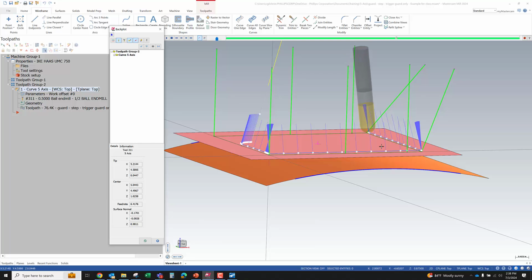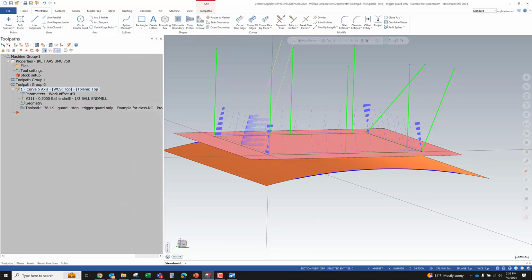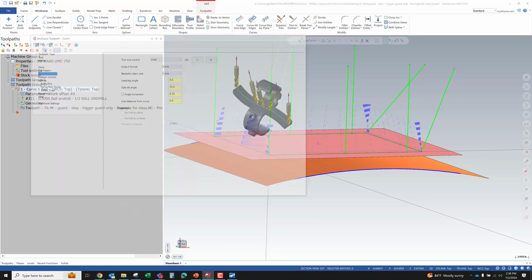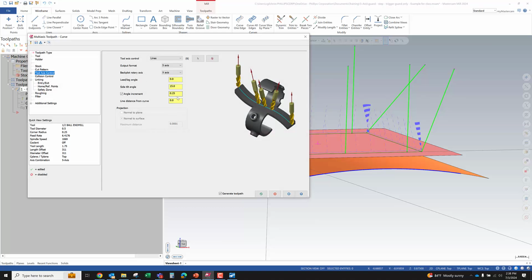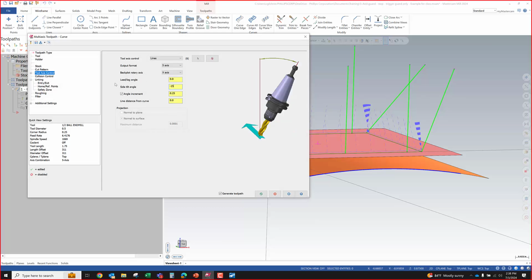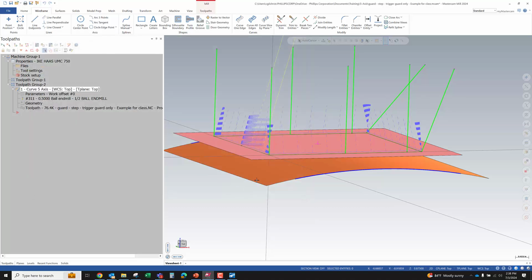again, keep in mind we've got to know what the direction of tilt is, or excuse me, the direction of our chaining direction plus what side we're on. But this is positive side tilt. It also, and the same is true for the lead and lag angle, will accept a negative value. So if I tilt negative 15 degrees,